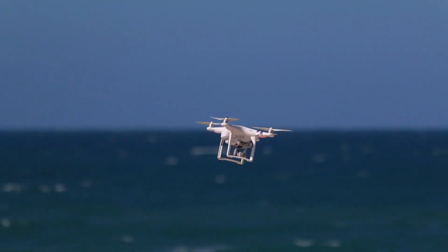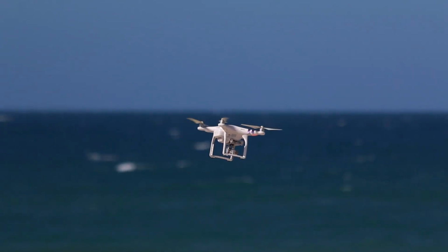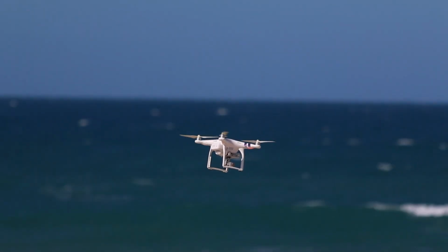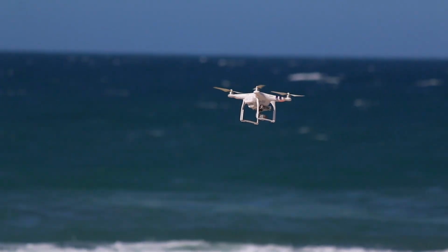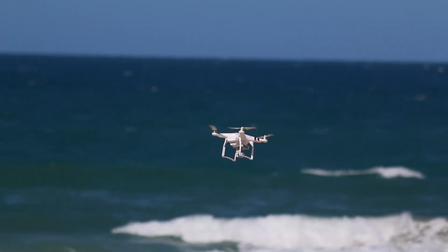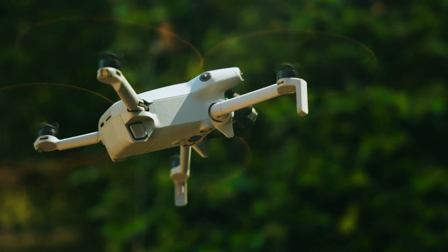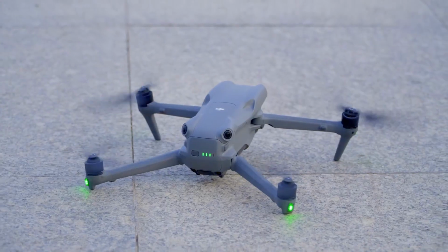The trade-off, on the other hand, is that flight time is limited. You're fighting gravity the entire time. Those motors are working hard. Most consumer quadcopters run out of battery after 25 to 40 minutes, and they're not efficient in wind. A strong gust will push them around because they're relying on rotor thrust, not aerodynamic stability.